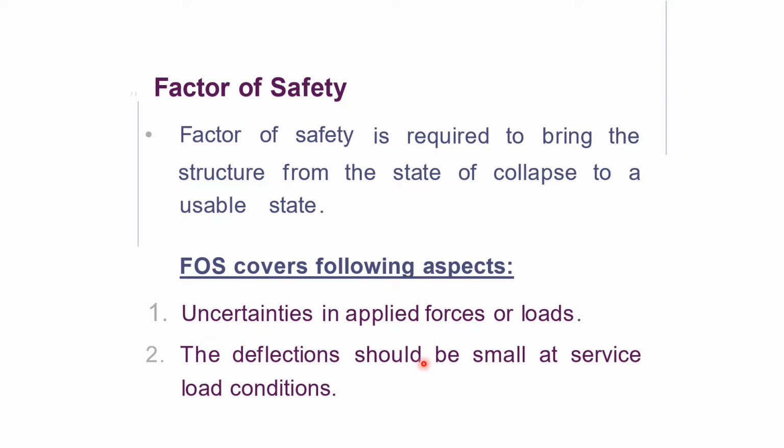The deflection should be small at service load conditions. When we have applied the factor of safety, for example, the requirement of the client is: please design my beam, my slab for 20 kilonewton, but we provide the factor of safety and design the beam against 25 kilonewton. So that's why there is a 5 kilonewton margin with which we have designed our member. So all these deflections will be covered under the factor of safety.